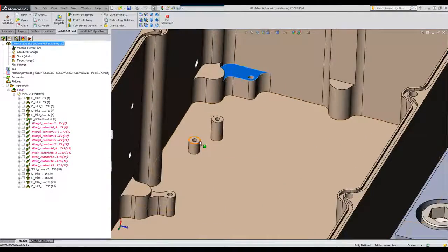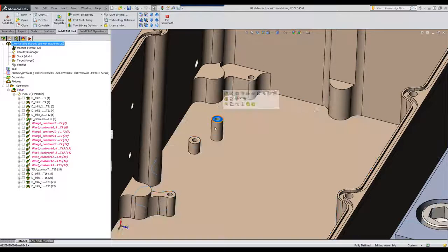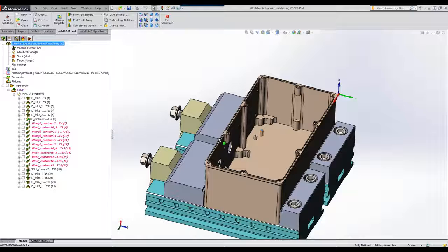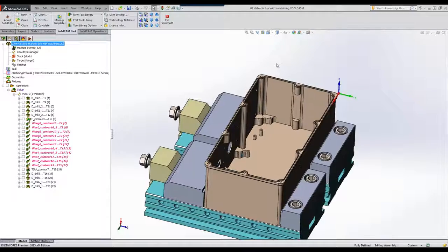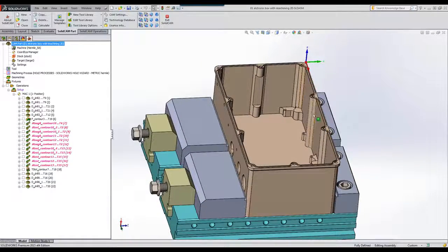We even have these two steps over here, which are not the same height either. So in order to do iMachining 2D for all of this, I have to do several different roughing operations to work efficiently around those areas and get to each depth individually. And for each area, I need a separate geometry.